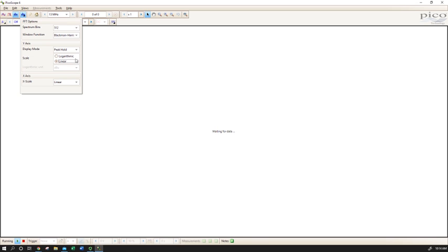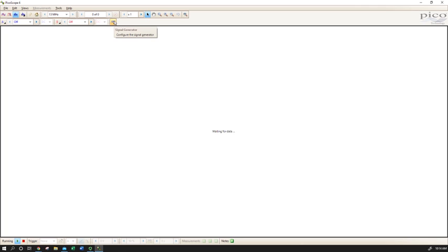Typically you would need a log scale for resonance, especially for radio frequency or for something with a high Q factor, but we're not going to get a lot of decibels of change. So it's going to be easier for us to see this with a linear scale. So these are our data collection parameters that just make it easier for us to see. Now, the choice then becomes, where do we think resonance is? You know, how big of an inductor do we think this is? Because for a given capacitance, the bigger the inductor, the lower the frequency we would expect resonance.